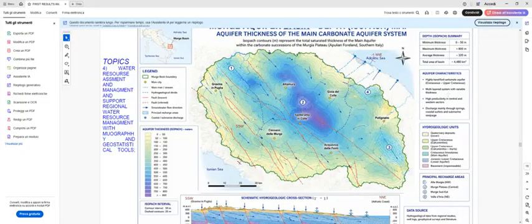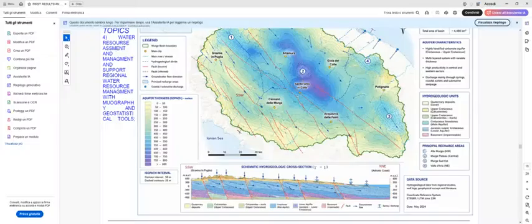As we just said, we have different parts that we can recognize. I classified the carbonate aquifer in this central part of the basin, Cretaceous and upper Cretaceous, middle layer, a system with variable thickness and high productivity in the central western sector. So the geological, hydrological and structural analysis is much more important to understand effectively what the maximum capacity of this aquifer to store water will be, what the preferential drainage lines will be, and what the actual behavior is.